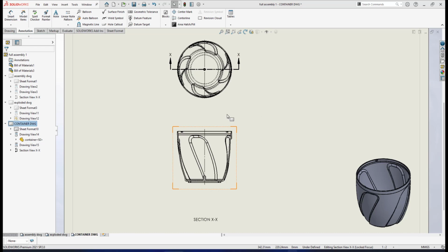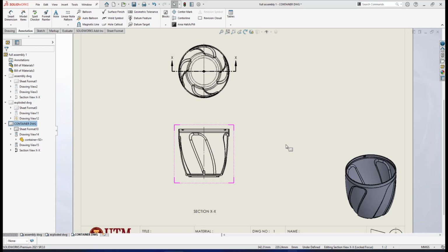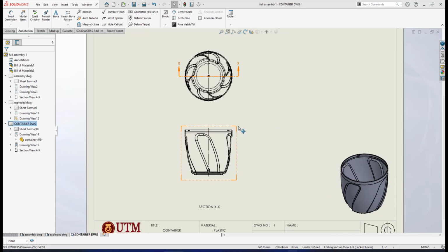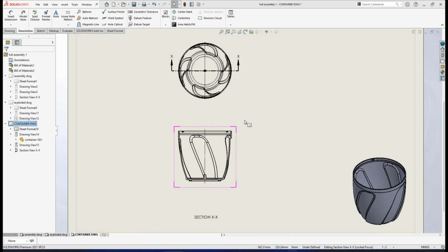your component is not this plastic container. Let's think like your part is a metal part, like a plate or a metal bar, which means your part will be manufactured by machinists. They will do drilling, lathing or milling. So the detailed drawing of that part must be detailed, because the machinist really depends on your drawing to fabricate your part for machining. So for this container, as I explained again, we don't have to put really detailed dimensions.